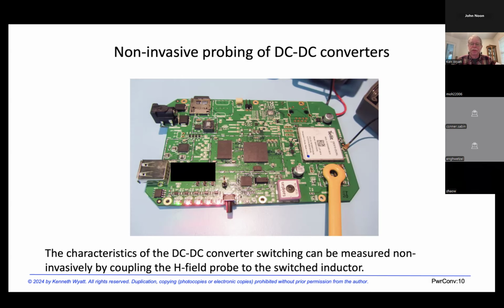But you can see in this example, the DC to DC converter is located right next to the cellular module. The manufacturer of that cellular module recommends doing that, but when you do that, you risk coupling the noise right into the cellular antenna or input to that module. And in this case, it was so noisy it could not acquire the cell towers.